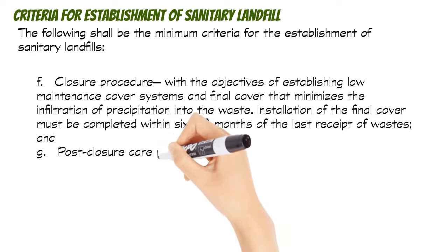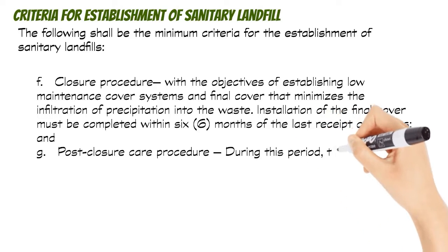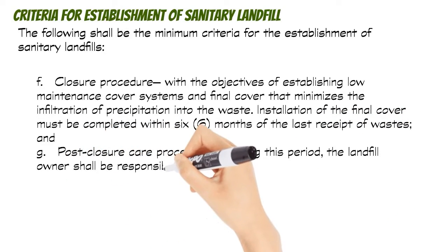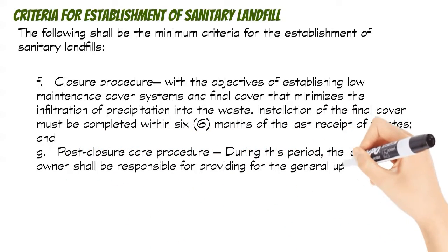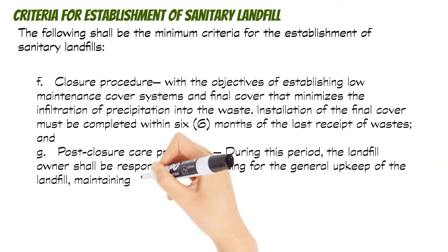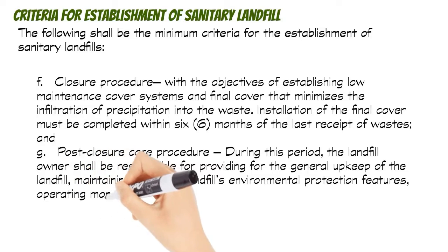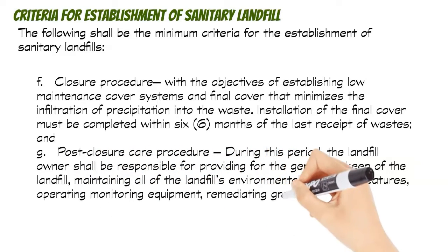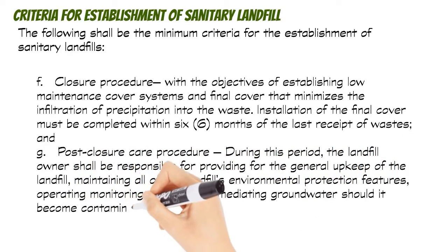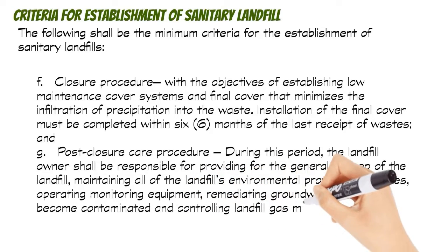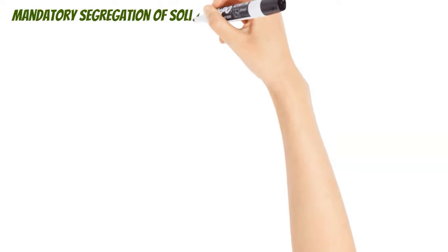And G. Post-closure care procedure. During this period, the landfill owner shall be responsible for providing for the general upkeep of the landfill, maintaining all of the landfill's environmental protection features, operating monitoring equipment, remediating groundwater should it become contaminated, and controlling landfill gas migration or emission.